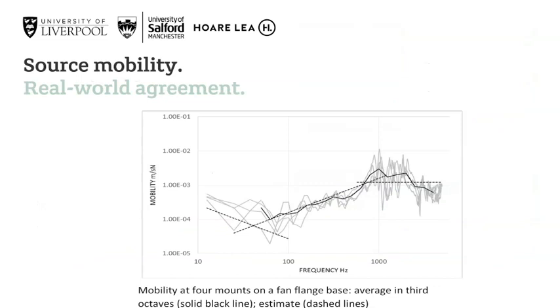And again, as we do, we step outside of the simulation environment and look at measurements on a real-world flange base. And we can see again that the three transitional areas of rigid mass, stiffness controlled from the cantilever supports, and infinite plate mobilities, again, draw a nice average line through the measured response. So again, our simple expressions provide a nice real-world approximation.